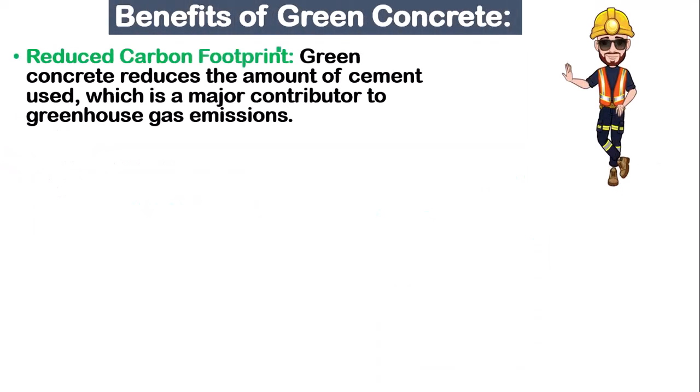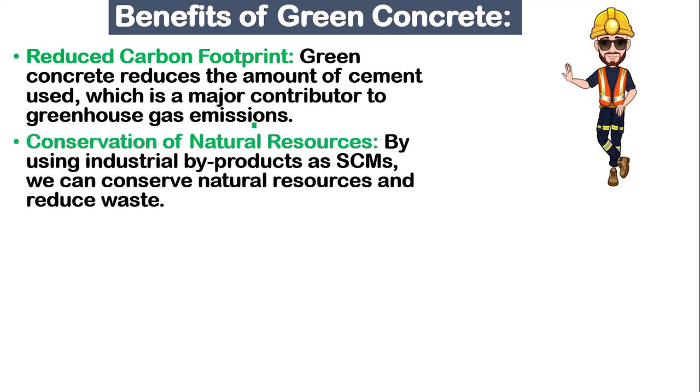What are the benefits of green concrete? It reduces carbon footprint. Green concrete reduces the amount of cement used, which is a major contributor to greenhouse gas emissions. The second benefit is conservation of natural resources. By using industrial byproducts as SCMs, supplementary cementitious materials, we can conserve natural resources and reduce waste.